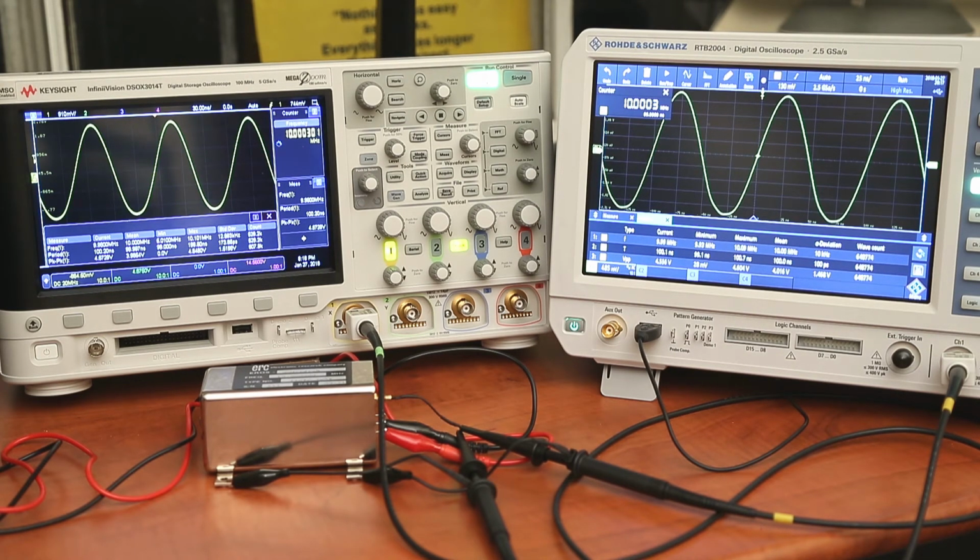The frequency on the Keysight, using the frequency counter, which has got the 8-digit specification, is reading 10.000300, and if we look at the Rohde & Schwarz counter, that's actually displaying exactly the same frequency, which is rather impressive, 10.0003. Obviously there's not as many decimal places on the Rohde & Schwarz one, because the counter on the Keysight is spec'd with an 8-digit counter because it has a 1.6 parts per million crystal oscillator, oven controlled one I believe, in the Keysight.